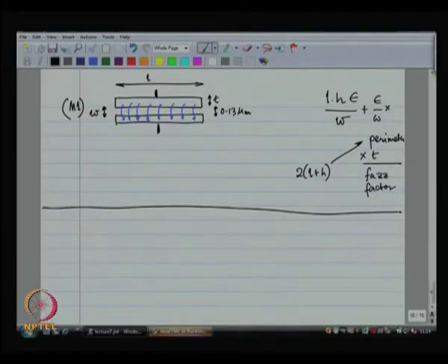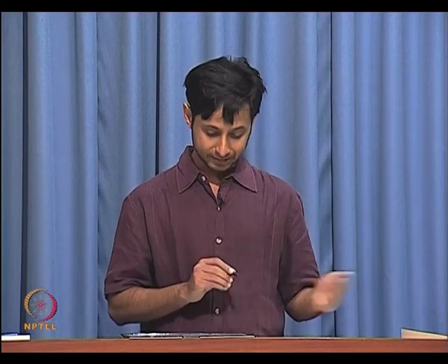So, how do capacitors like this look? Let us say I want to make a capacitor between 1 and 2. Oh, what about parasitics to ground? Both of these will have equal parasitics to ground, right. They are equally far away from the ground plane, whichever metal layer they are in. If you use the topmost metal layer, then they have equal parasitics to ground, but lesser.